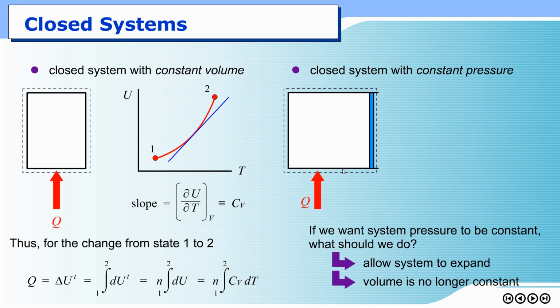Okay, and from this picture you will see that the expansion here is obviously expansion work. So the system expands, that means the system is doing work, and this particular work is expansion work for sure. Assuming that we don't have any stirrer, we don't have non-expansion work in this case, and we don't have electricity, so we don't have non-mechanical work. The only form of work that we consider is expansion work for this particular derivation.